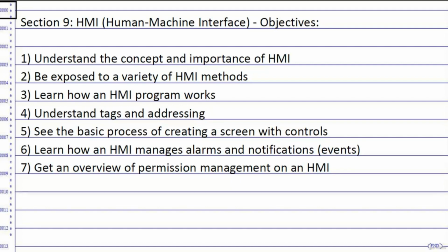Beginning with tags, there's addressing them to the PLC, establishing communication, whether it's with an IP address or the name of a processor in RSLinx. That just depends on the platform. After that, setting up displays shouldn't be any problem.